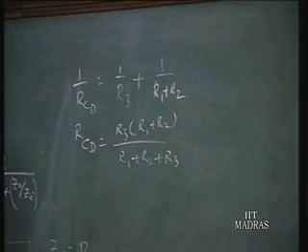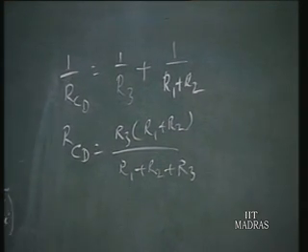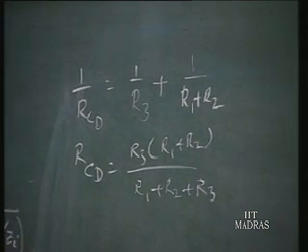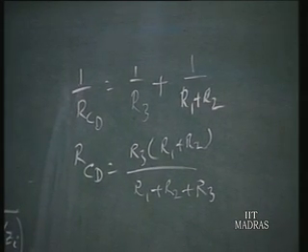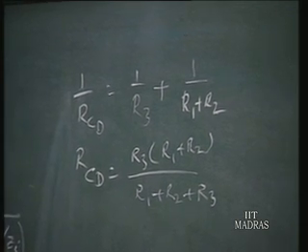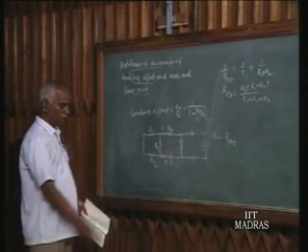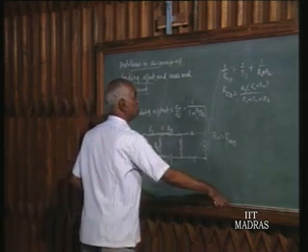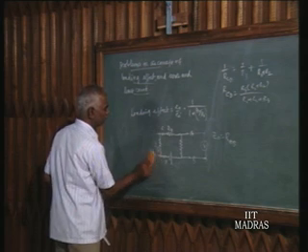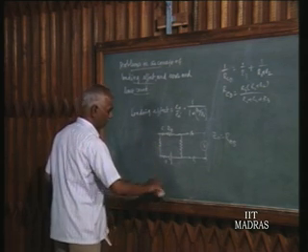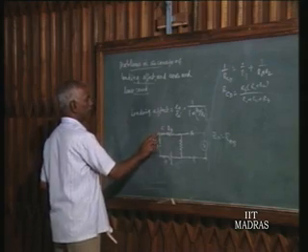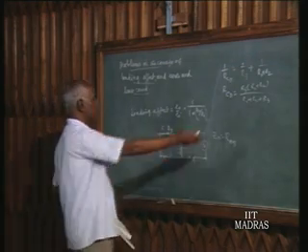So simply we say, for parallel paths of two resistances RA, RB, RAB is equal to RA into RB by RA plus RB. That is the formula we have used here, finding the equivalent resistance of two parallel paths. Now I can forget the circuit and instead simply write this as RCD. R3 with the rest I can write as RCD, because its equivalent value I have put here. The whole circuit is put as RCD, whose resistance is so much.